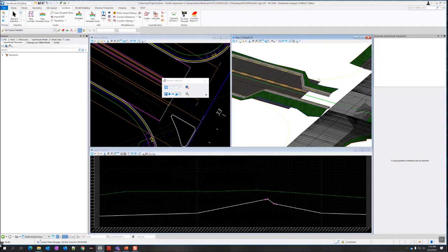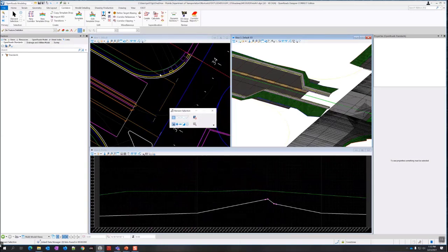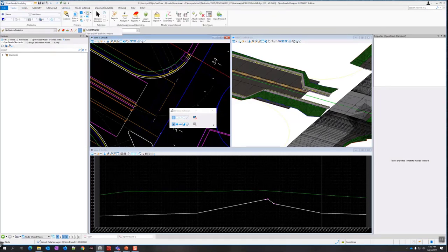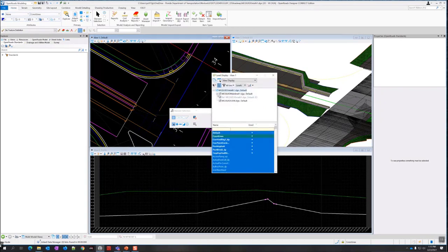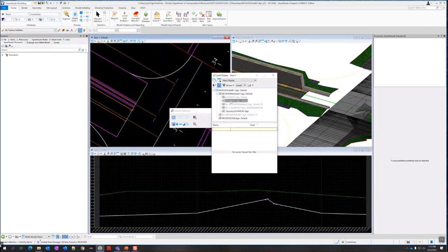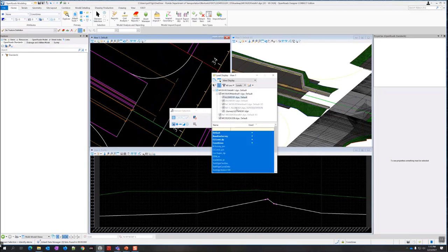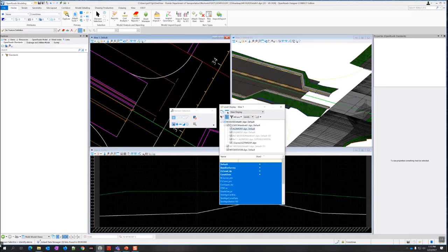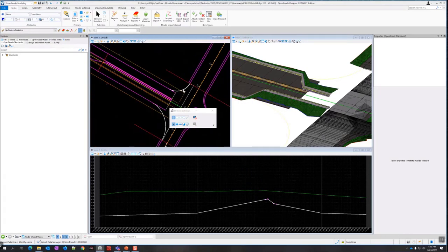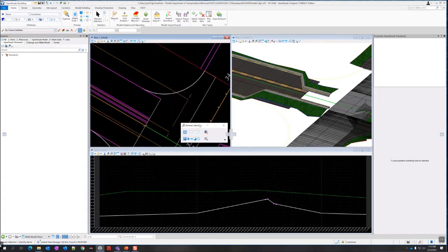So we have everything set up here. We have our 2D and 3D geometry for this. Just to clean this up a little bit, I'm going to turn off the DSGen RD reference. I'll come over here to the level display and expand out the mainline 61. Turn off the display altogether, DSGen RD01. We'll turn alignment back on. It doesn't save the settings because I have the nested references on that. So now it's going to be easier to select these lines here to make these edits.